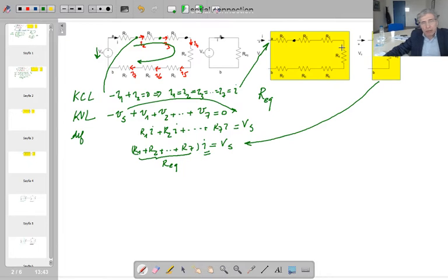The next step is, what's the use of that? First of all, if you consider 2 elements connected in serial, and you replace those 2 elements with an equivalent resistor, then one of the nodes will disappear. That means you are not going to write a Kirchhoff current law equation for this node. If you remember, in the analysis we use ND minus one Kirchhoff current law equations, NE minus ND plus one Kirchhoff voltage law equations, and the NE definition relations, totally 2 NE equations.